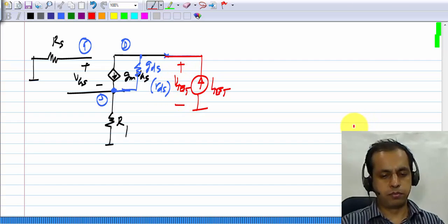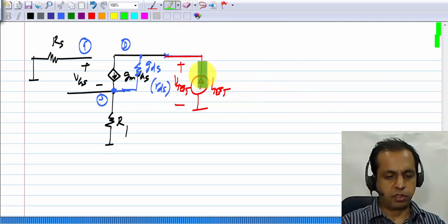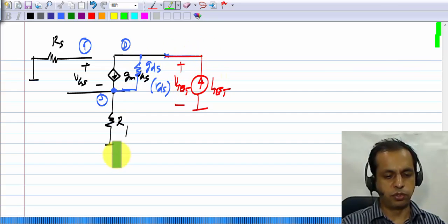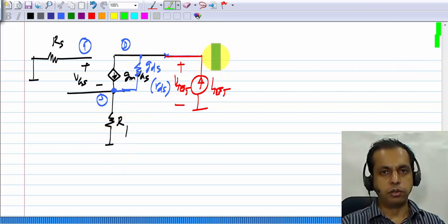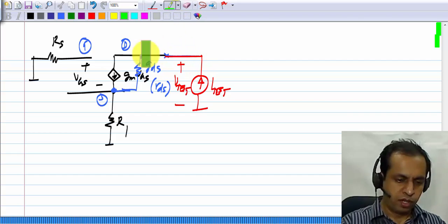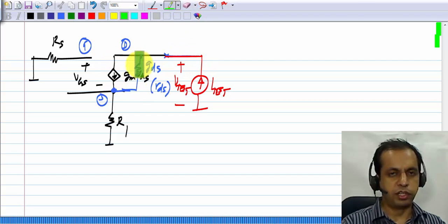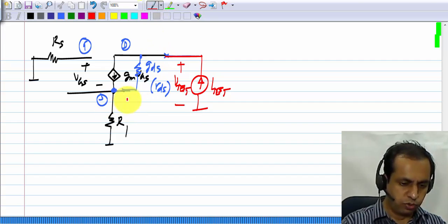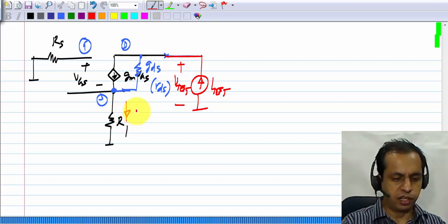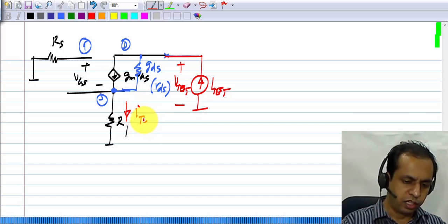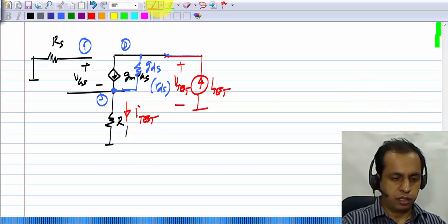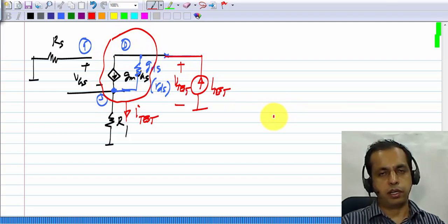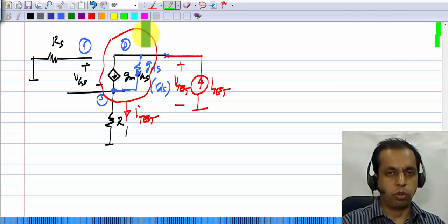Okay, now the easy thing about using a current source is that when you have a number of series paths, the same current flows through all of them, and that can lead to some simplification. We don't know how much current is flowing here and how much current is flowing there, but whatever goes into this has to come out here. So it should be very easy to see that the current here is simply equal to Itest. Again, you can imagine that by writing down Kirchhoff's current law around that whole circuit.